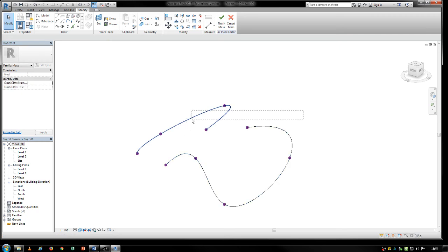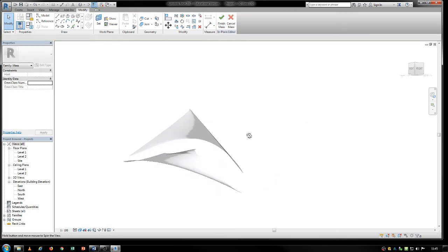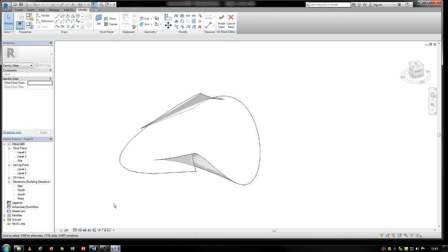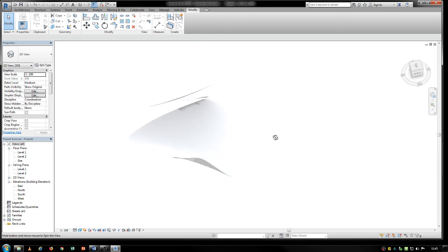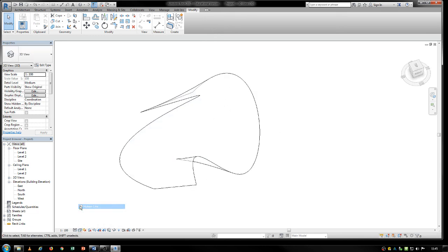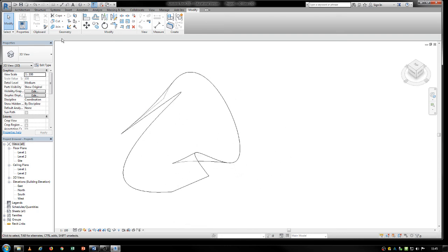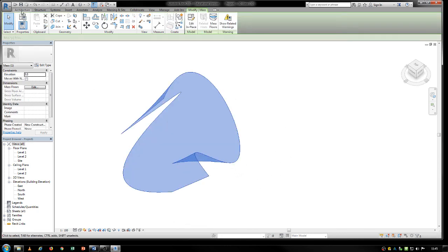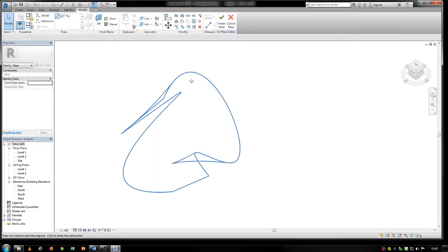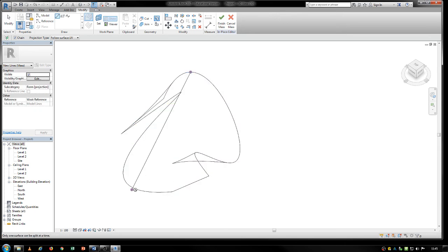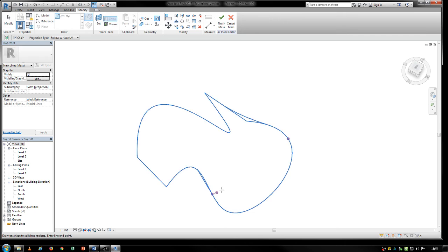Then when I select both of the curves and say create the form, it's going to do this kind of thing for me. When I say finish, I don't know how visible it is, but it's creating that form for me. Now I can use this to make my wall by face and that kind of thing. Now the split face should work. So if I go in and click on these, it's reading this nicely. So I can go in and connect to